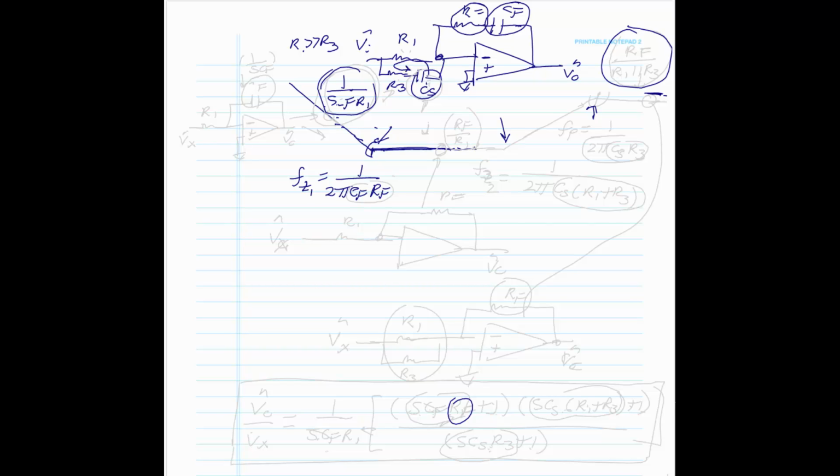At this point, you've got to understand what the circuit is. Always draw the circuit which it looks like, and that'll really help you. So this becomes CF, and this becomes R1, and this is Vx. Right away you can see the gain is just this over this. How do you write this in impedance form?